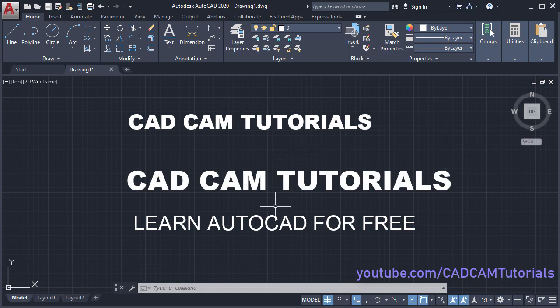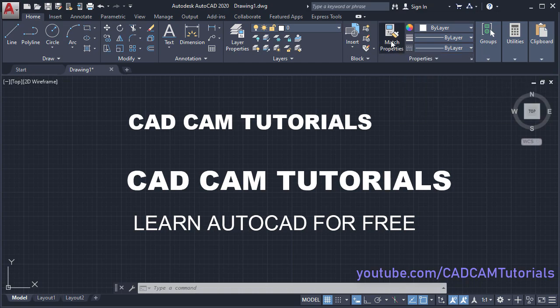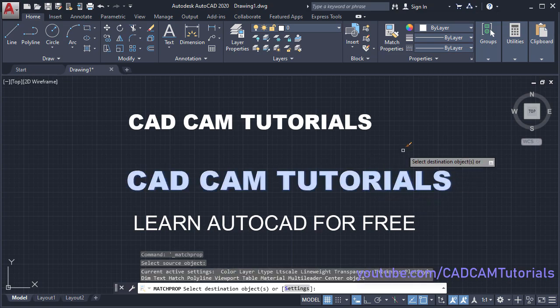Then if you want to match properties of two text, then you will have to use match properties. Keyboard shortcut for match properties is MA enter, that is first two characters of match. Then click on match properties. Then at first you will have to select source object. Source object is the object from which you want to copy properties. So I want to make this text like this. So this will be our source object.